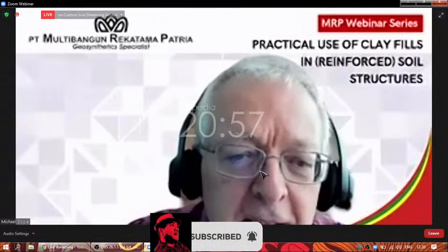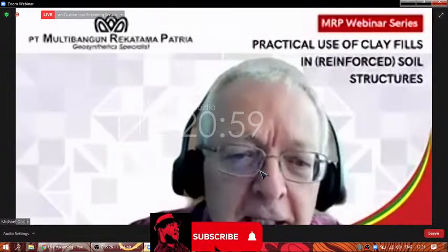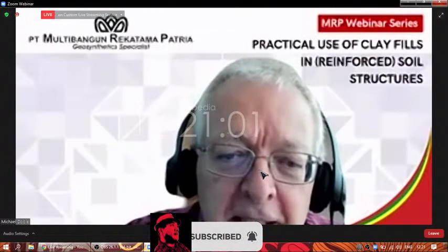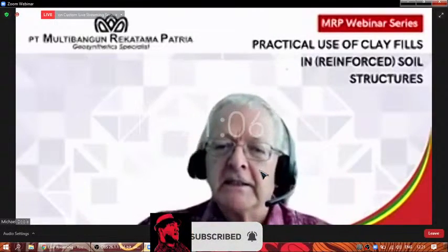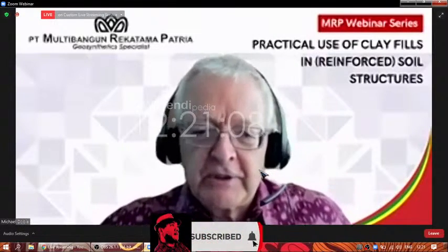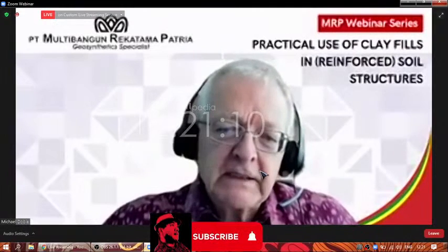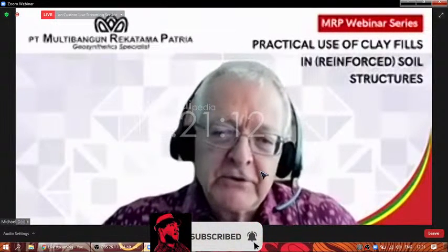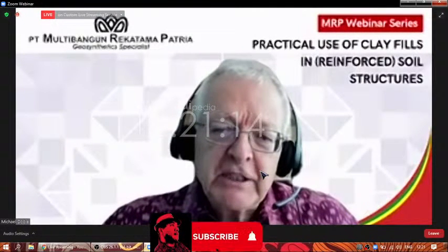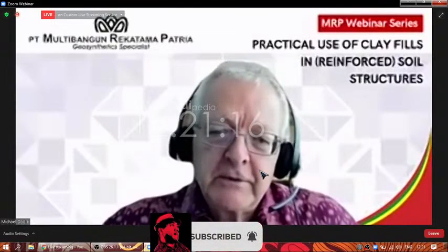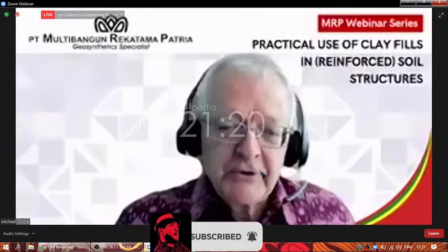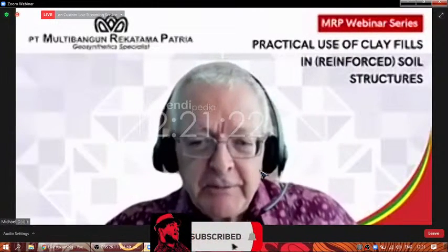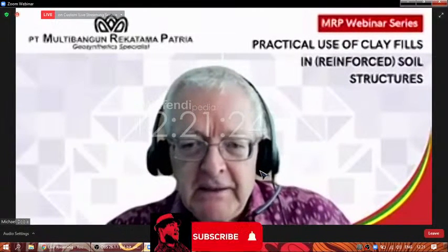Then we have Hui Sui Han Wong. Should drains be kept at an angle to ensure that water can be drained safely? I think, yes, crossfall is a good idea, if it can be arranged. Just think about one thing. If you're building an embankment over a softer soil, then the settlement of an embankment will tend to be in a dish shape.